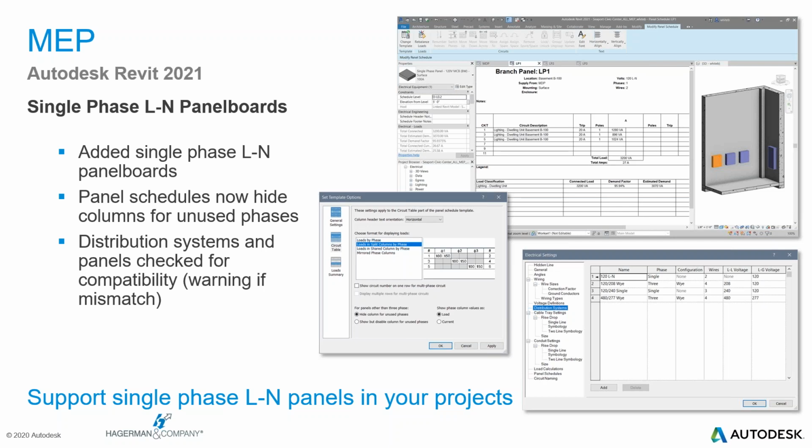All LN panel loads are on a single phase, and the phase total loads tabulate accordingly. The panel schedule will show the loads on the phase defined by what phase it is connected to on the panel it is fed from.